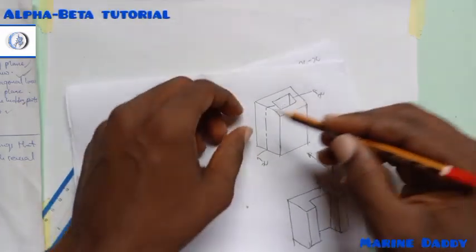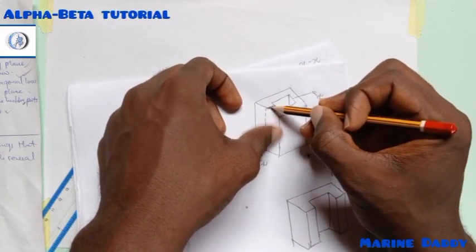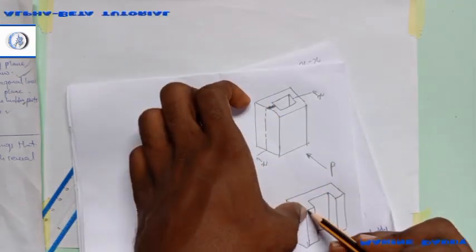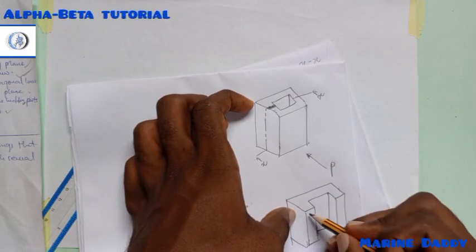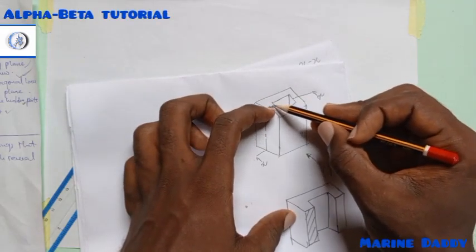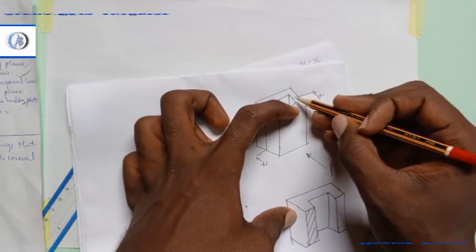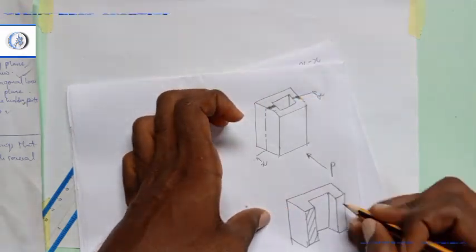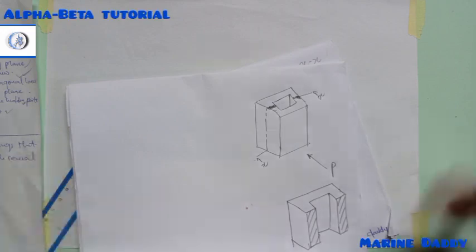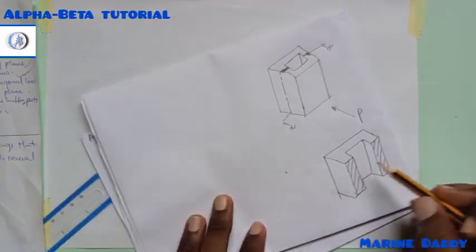Now, based on what I said earlier, this knife will cut through this part, and also cut this side, because here is a thick place, the thickness of the walls. This thickness is the part that the cut passes through. So it is supposed to look like this. This side, the knife does not reach, because here is a hollow place, so the knife does not pass through this other side. So here will remain blank. But this side is affected, making it also a rough surface. But like I said earlier, this is not the right way of representing a section. So the right way will be in this manner.